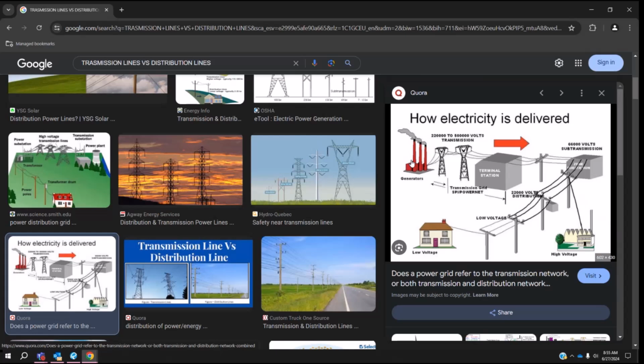Not impossible, we do it pretty commonly, but especially way back in the late 1800s, going from 24 volts DC to 60,000 volts DC, you're not going to do that. That would be hard even nowadays, setting aside all the additional problems that come with conductors and whatnot. The idea of needing to go a couple hundred miles, AC is literally the only way to do that at the moment.